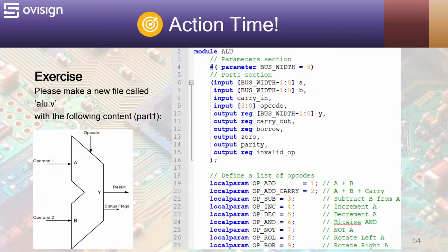Because the Verilog files have many lines, I've split the code in half for each file. The module has two 8-bit input ports for the operands, one 4-bit port for the operation, and one 8-bit output port and some flags. We will use a parameter to make the design adaptable to changes.